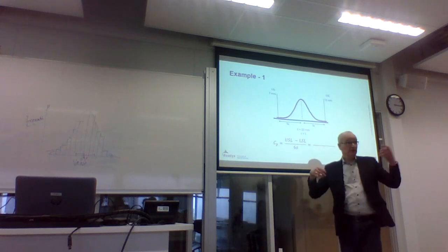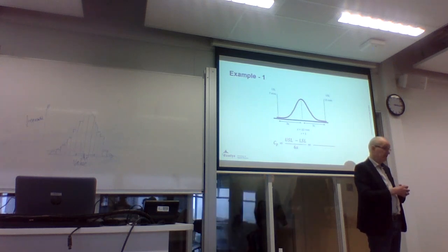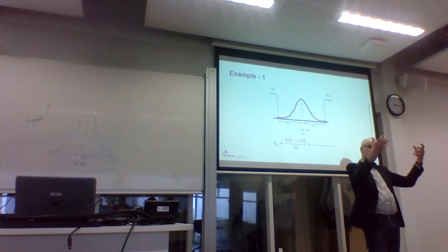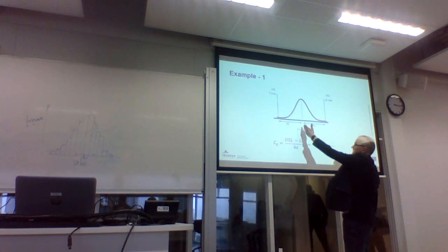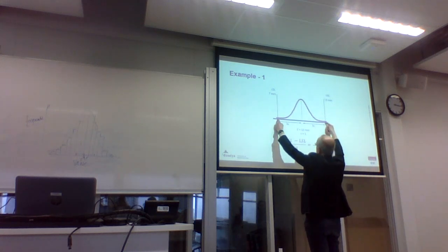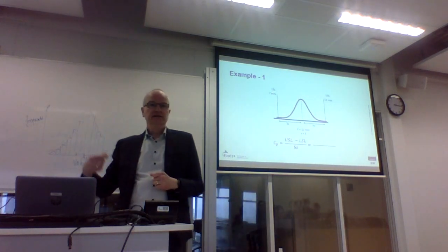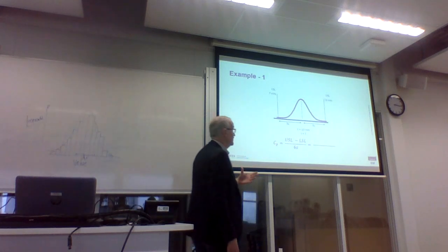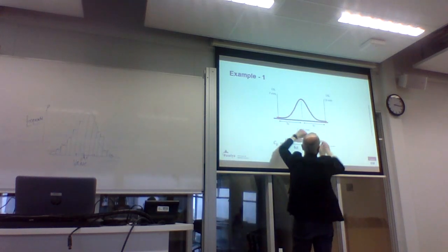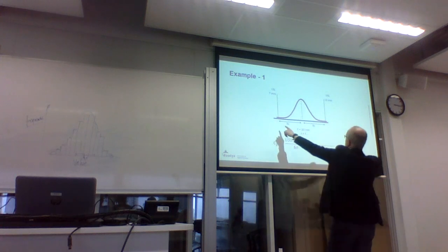And I have a standard deviation. I looked at the past, I measured all the diameters that I've drilled, and I see that my average distance to the average is 1 millimeter. So my standard deviation is 1 millimeter. And I know it's normally distributed, a nice bell-shaped symmetrical curve. So the average is 10 and my standard deviation is 1, and then I know that this area, plus or minus 3 sigma, 3 times the standard deviation, is the 99.7% that we were talking about. So this is a result of my process. Well, my customer says, I only accept holes that are within 7 and 13 millimeters.